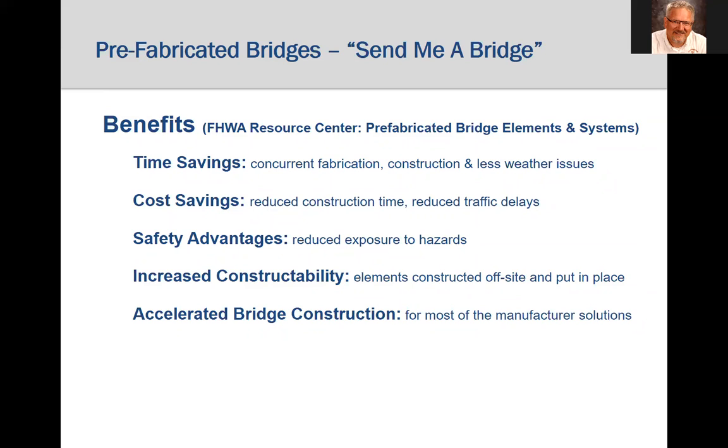They are built into components, modules, and assemblies in a quality-controlled shop, shipped to the bridge site, and erected. This results in time savings for construction, cost savings, increased site safety, and the pieces will fit together really nicely because of the quality shop fabrication.